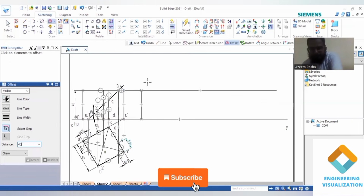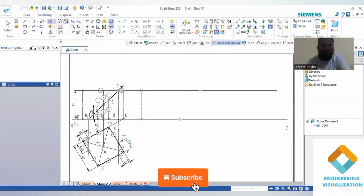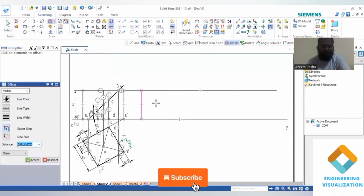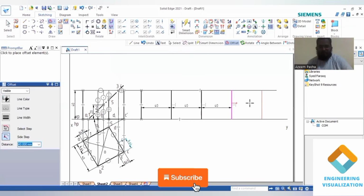From that vertical edge I'll be considering a distance of 40, enter. So the wrong side I have considered. You need to consider the right side. 40, enter, click OK, and then you get the 4 faces here.